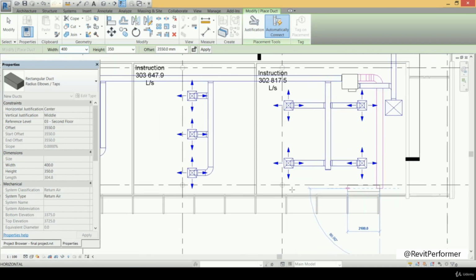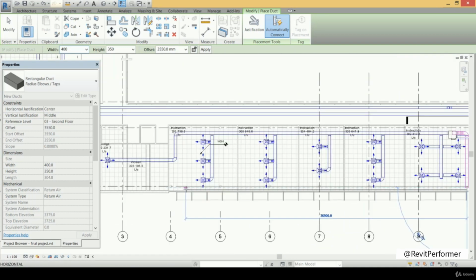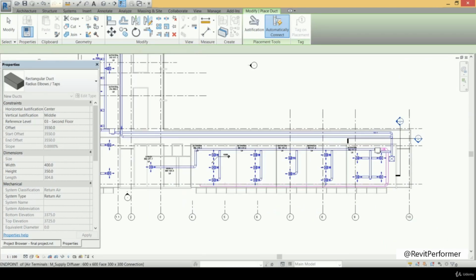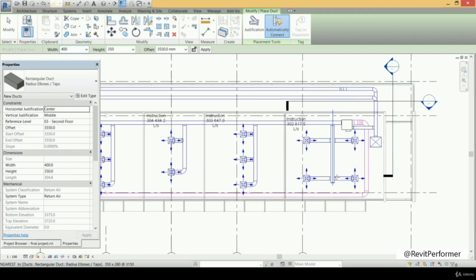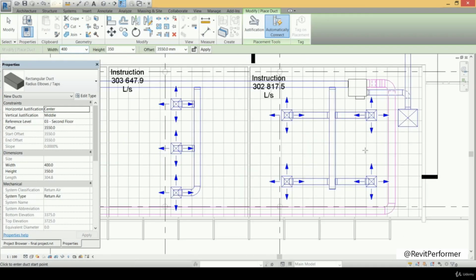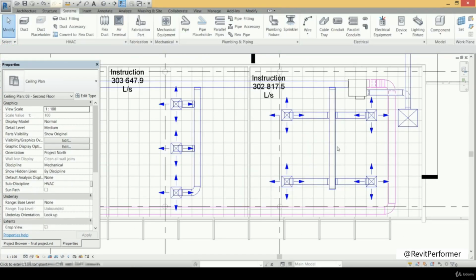Here we can go forward to insert the duct until the last space that we have, as the return duct, or the main return duct, will enter all these spaces to absorb the air out of all the return diffusers that we have. Also, the second notice is that we can distinguish easily between the return duct and the supplying duct with their color. So the supplying ducts are in blue and the return ducts are in cyan color.